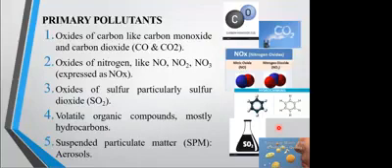There are 5 primary pollutants that contribute to 90% of global air pollution: the oxides of carbon, like carbon monoxide and carbon dioxide; the oxides of nitrogen, like NO, NO2, NO3, generally termed NOx; the oxides of sulfur, particularly sulfur dioxide; the volatile organic compounds, mostly hydrocarbons; and of course the suspended particulate matter, or SPM. Examples are the aerosols.